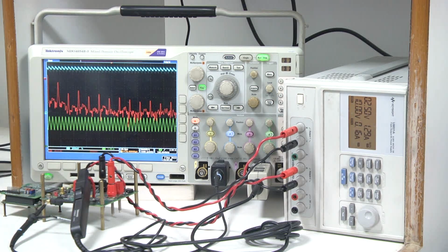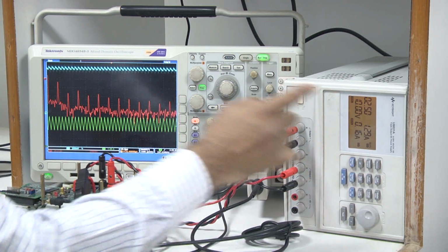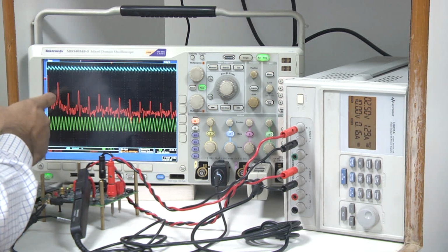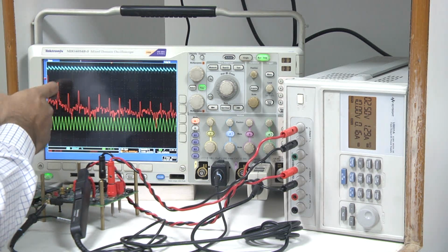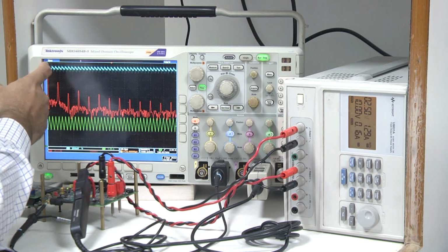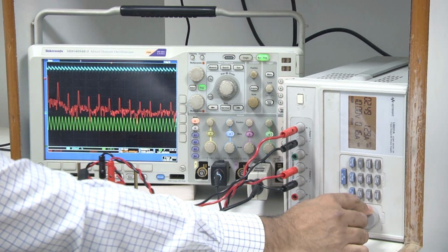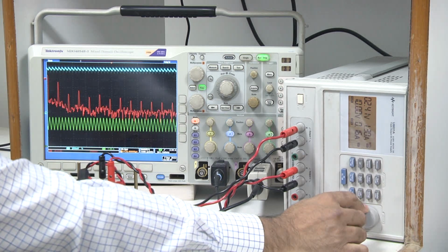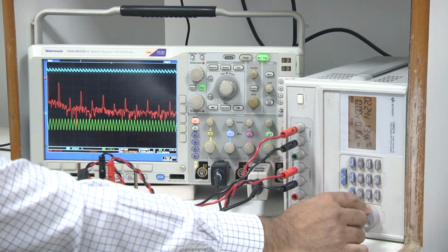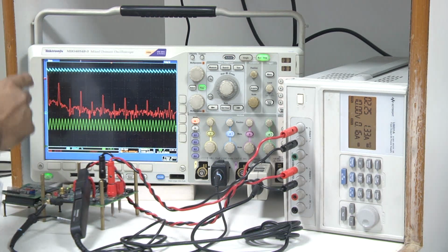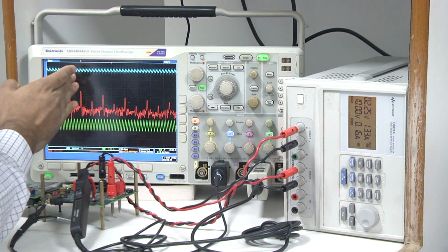Now we are changing the input voltage. At 2.5 volt, you can see this frequency is more or less 200 kilohertz, because the first peak is coming, the fundamental component here. This is the average current, then the harmonics are coming. Now once we go to 2.25 volt input voltage, you can see it is perfectly stable, and the frequency is slowly moving towards this.